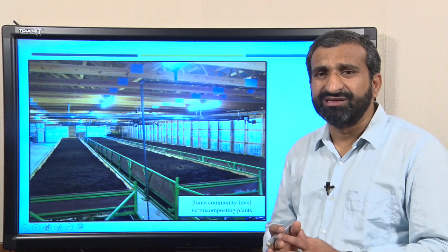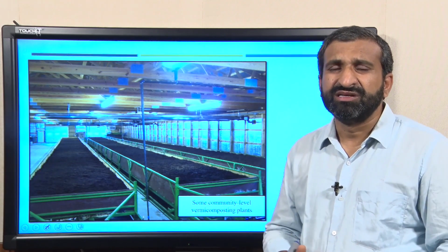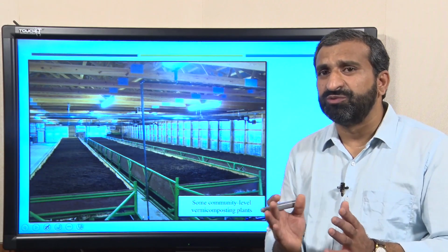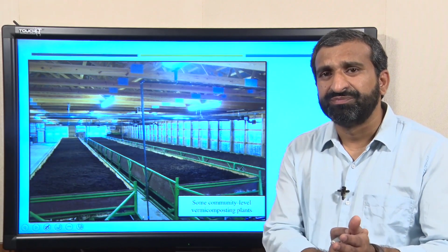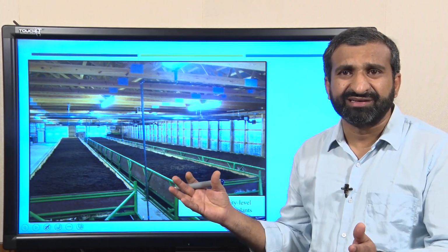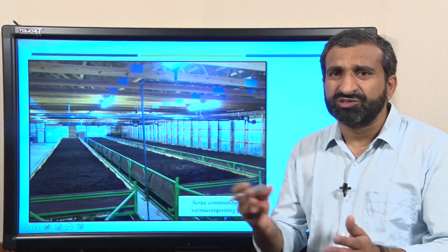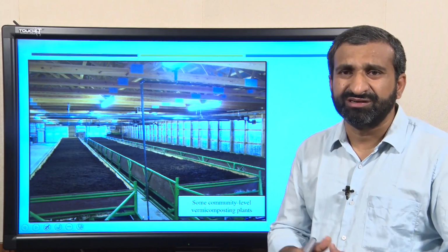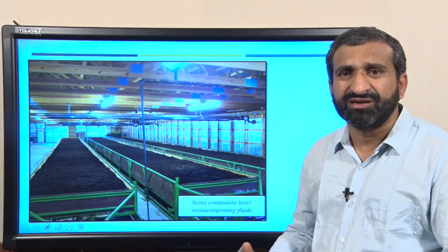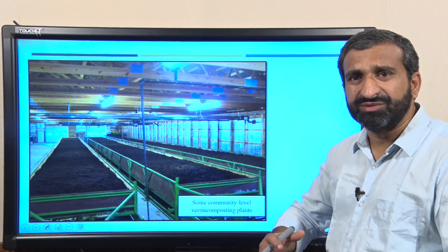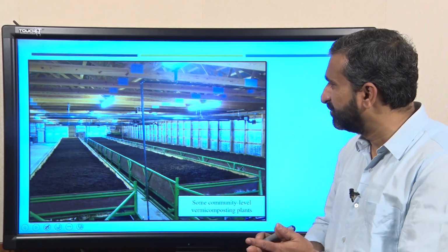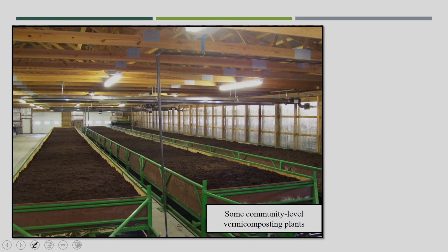And if you see, especially in India or developing countries, the quantity of this waste is more than 50 to 60%, and if you are able to reduce this 50% at source itself, maybe at household level, apartment level or community level, we can easily treat the dry matter at a centralized facility. And also, you know that we do not have space for the disposal site, and because of degradation of this waste at the disposal site, a lot of issues are coming with groundwater pollution. So because of this kind of decentralized treatment process, we have a lot of advantages.